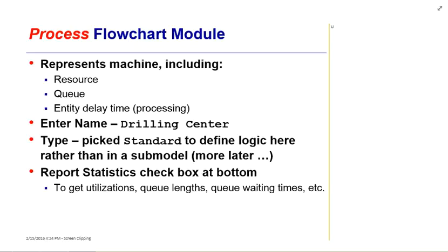And then finally, the distribution, or how things are processed through that process, is your last box there. It can be a statistical distribution. You've got units, same thing, keep them the same. You can do a little value stream mapping right within Arena, allocating whether the process you're looking at is value added or non-value added.